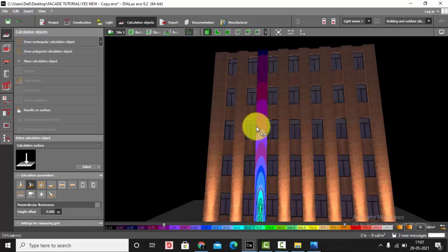So this was about placement of uplights for the solid facade and the vertically divided facade. We chose two different fixtures for this application depending upon the heights of the facade, and we also decided different optics. Also saw about selection of the CCT for the luminaires.